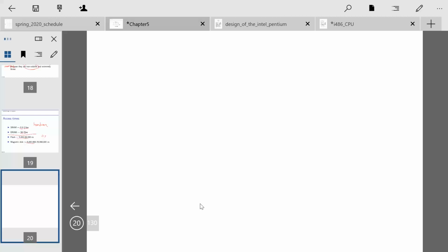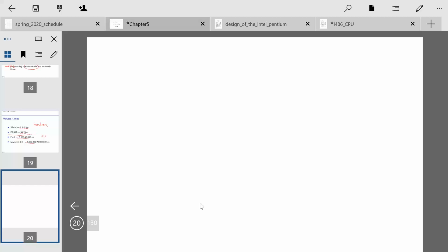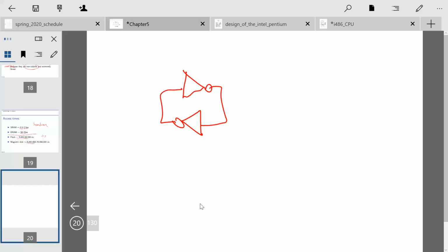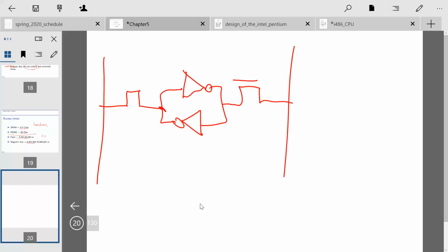Okay, all right. I have a little space here because I just wanted to remind ourselves of what these different cells look like, just so we can put it all together. So this is our SRAM. It's cross-coupled inverters, and then we have these pass transistors, and they connect to the bit lines, and we have B and B complement.